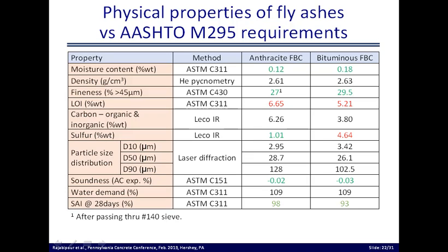Particle size and soundness are pretty good. The water demand is a little bit on the high side, but still not excessively large. And the strength activity index is in the 90s: 98% for one, 93% for the other.